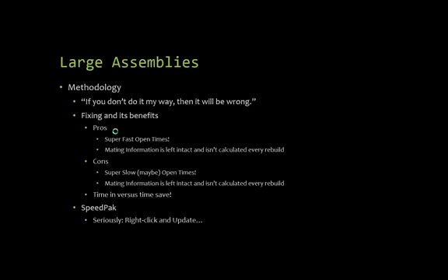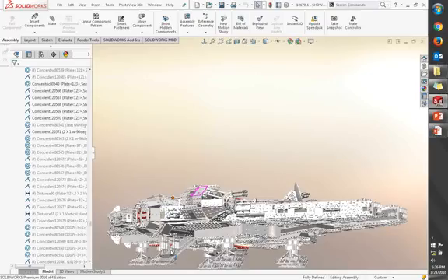So you'll see that a lot of these have Fs next to them. Now, as we go through, you'll see that some of them are still active. They're a little bit darker and stuff like that. A lot of times, these are parts that still need movement. Like if I look down here, I've got the little docking door that needs to move up and down. Those are mates that I would keep active at that time. I wouldn't fix that component.